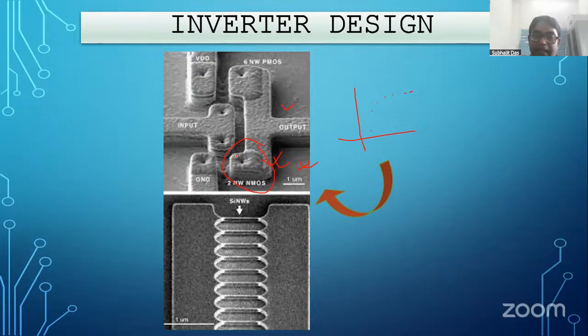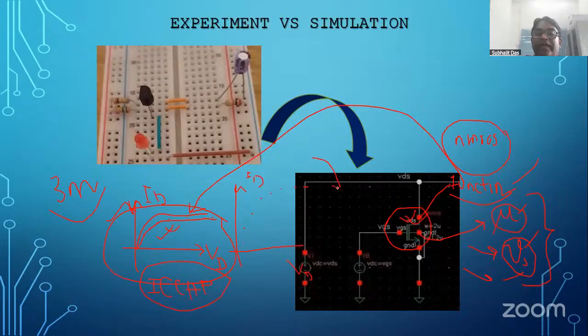Similarly, this NMOS is fabricated, and they have generated this experimental result. Then my program gets this kind of result, and I fit my program to the experimental value. Now I can say this MOS and my MOS are basically the same, a clone or dummy of the original fabricated MOS. Similarly, we model this PMOS, this nanowire, everything, and give it to the Cadence.